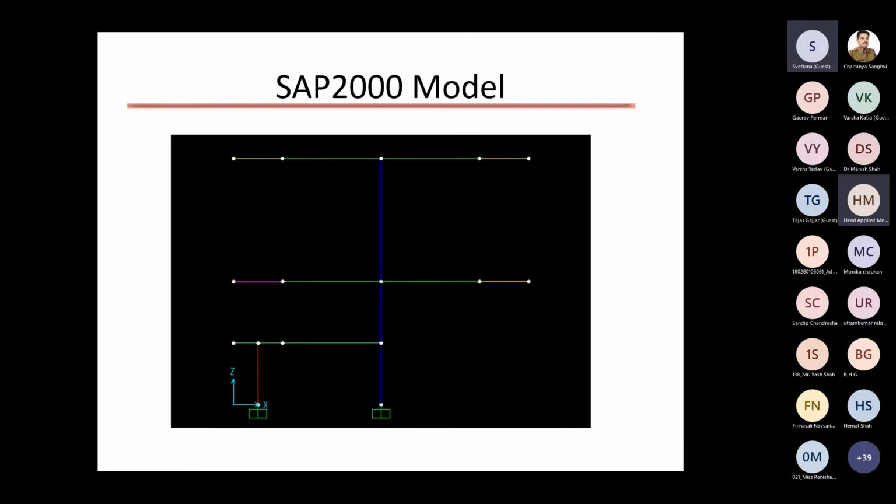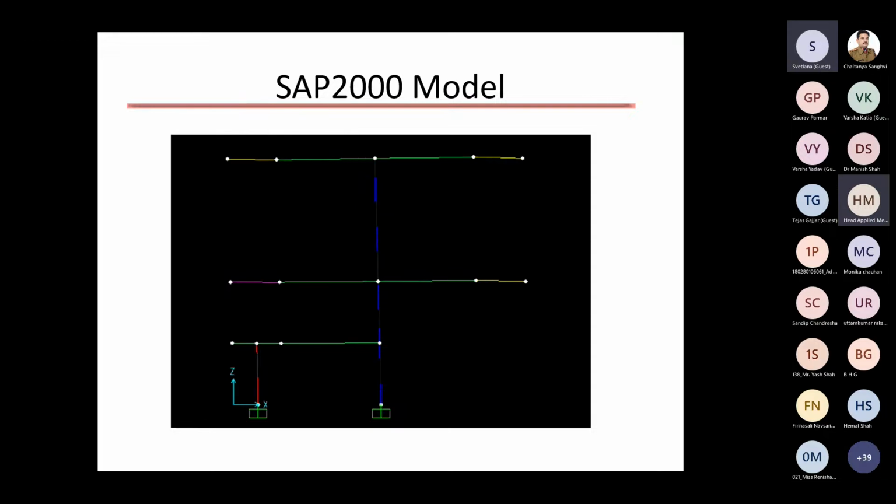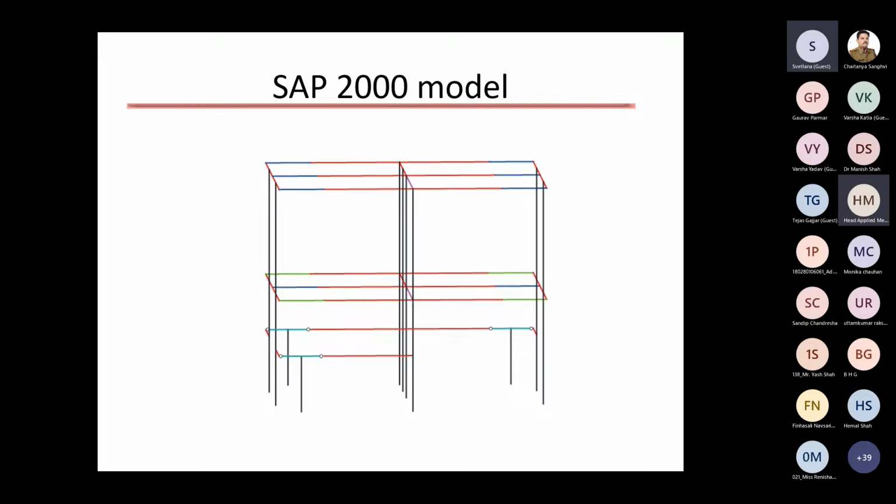The next diagram is showing the deformations of the model. The model was analyzed by response spectrum analysis. And this is just showing the deformed shape, so you can see how everything works in unison. The main point I would like you to take from here, actually there are several points about modeling certainly, but the point is that you can see that there is no separation between tie columns and the masonry.